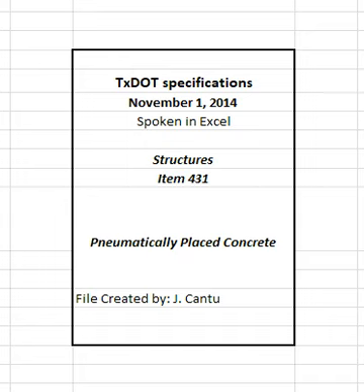3.5 Construction joints. Use a square butt joint where the joint is subject to compressive stress or is over existing construction joints unless noted otherwise on the plans. Use tapered or square butt joints at other locations. Square the outside 1 inch of tapered joints perpendicular to the surface.